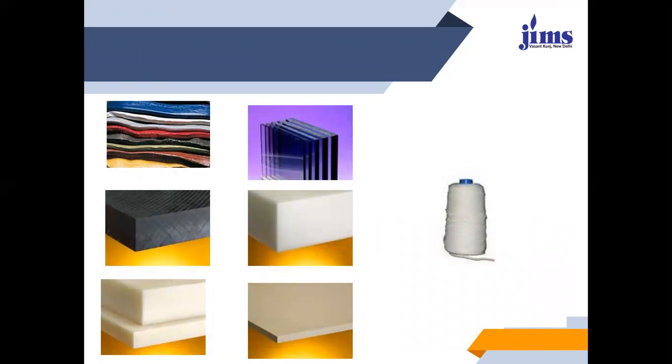Different color combinations are available here. This gives you the insulation after placing all the windings. Then we have to tighten the conductors with each other so that they never move away from the body. So we provide a threading structure which isolates the conductors and the insulation from each other, and it never moves out while we are transporting the transformer from one place to another.